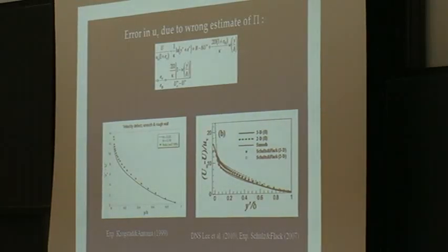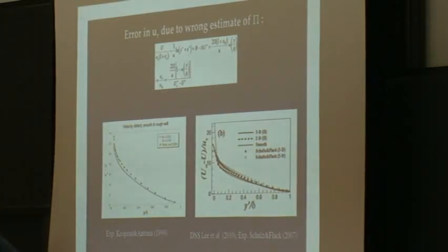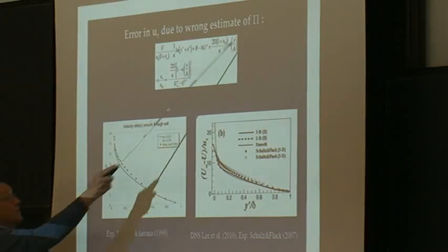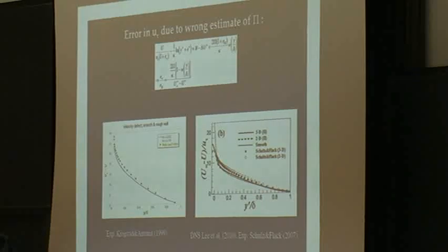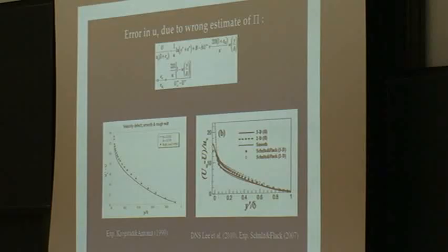My data, which goes back about 20 years, seems to support the finding of Tani that pi, this wake strength, is different on a rough surface than on a smooth surface. It could be that the high value which I got for my pi, which was about 0.7, was caused by background turbulence or some physical things in the wind tunnel, but I don't think so, since we got different pi's for smooth and rough walls.